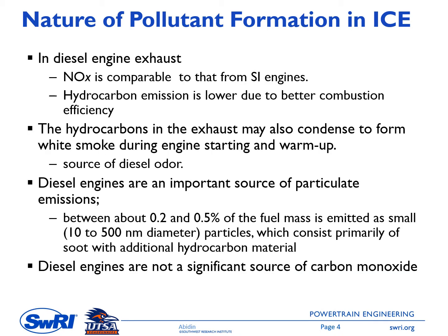In diesel engine exhaust gas, we have NOx that is comparable to that from spark ignition engine. There is also hydrocarbon emission, although it is lower due to better combustion efficiency. So we have lean mixture combustion process in the diesel engine that results in higher combustion efficiency than that for the spark ignition engine. The hydrocarbons in the exhaust may also condense to form white smoke during engine starting and warm up, and this is the source of diesel odor.